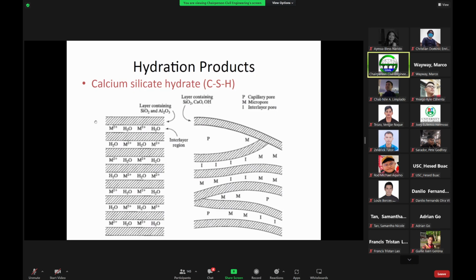So in some clays, these layers can be expanded to accommodate additional water. I don't know if it was discussed in your geology subject, but when you have clay as a soil, it can retain water very well. If you increase this water layer, it's going to expand your clay. And if you decrease this water layer, it will also shrink your clay. So a lot of loss of interlayer water when your clay dries will allow the layer to collapse and these silicate layers to contract. This will result in clay having very large volume changes when it's wet and dry.